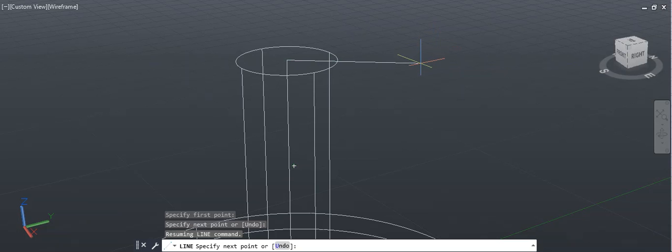And here is the way to do this in AutoCAD. The @ symbol, you need the @ symbol here because you already picked the first point. Because you already picked the first point, the second point should be in relation to the first, so relative coordinate entry has to be used. So type @, type 0, comma, and how long is it supposed to be? 0.5, right? So @0,0.5, and the enter key. Ta-da! All right, the first line has been drawn.